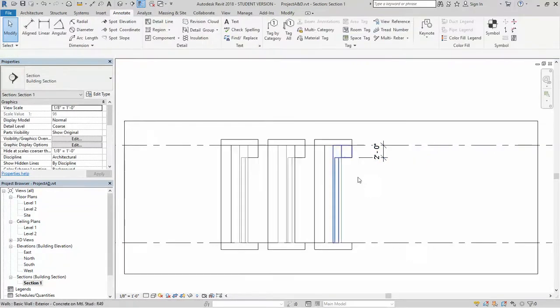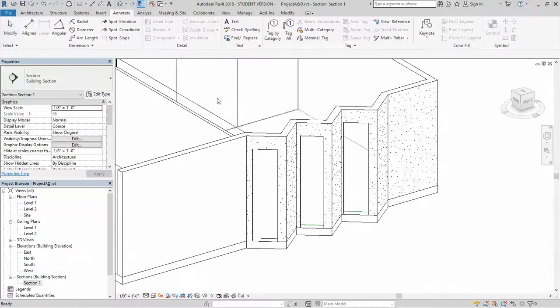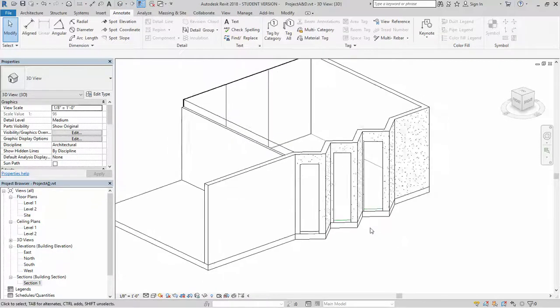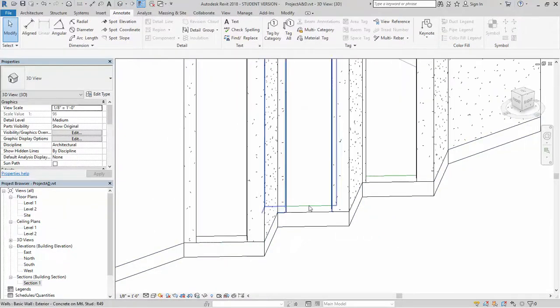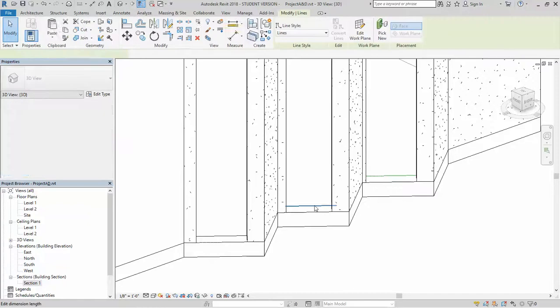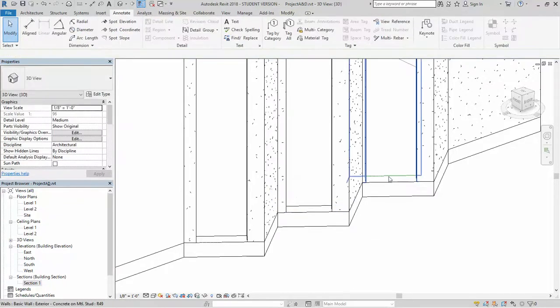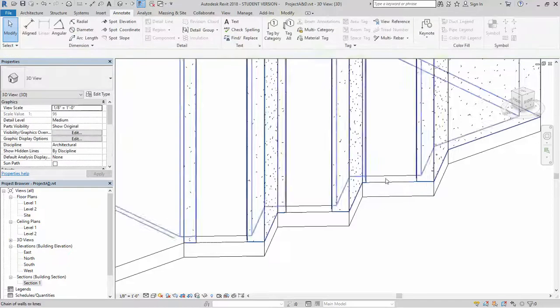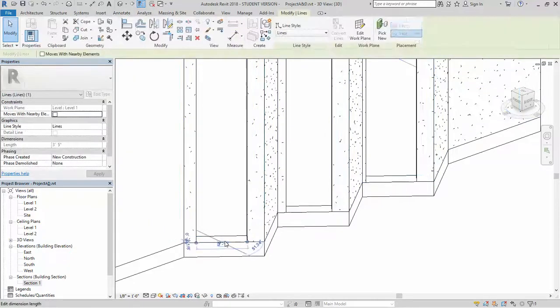If you go to the 3D by clicking on the little doghouse, we have all of the openings here. We also see the green lines, so we can select them carefully because you might just by accident select something else. If you want to select something that is difficult to select, just click on the tab one time after another until you get a blue signal that that's the object you want to delete or select. So you can press tab, delete. And in this case it's here, delete.